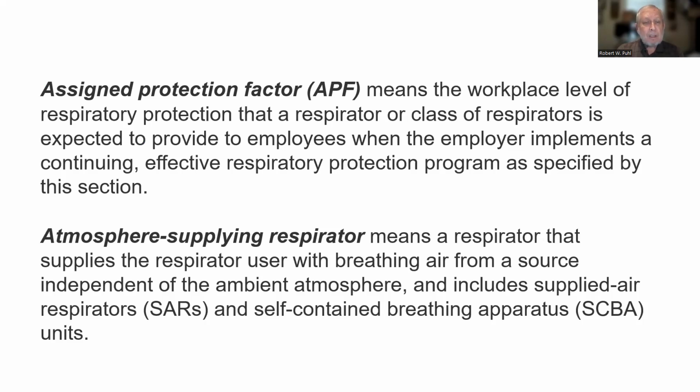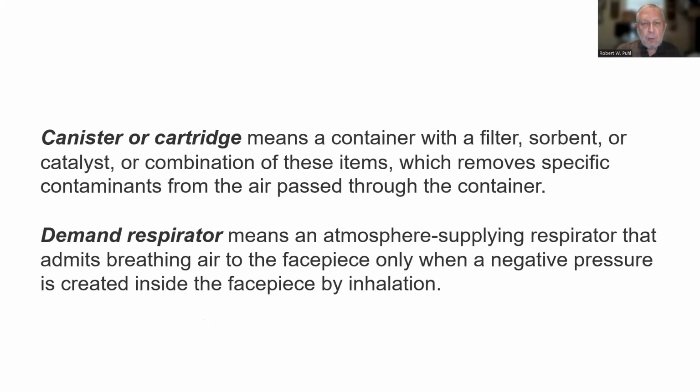Atmosphere-supplying respirator means a respirator that supplies the respirator user with breathing air from a source independent of the ambient atmosphere, and includes supplied air respirators, SARs, and self-contained breathing apparatus, SCBA. Canister or cartridge means a container with a filter, sorbent, or catalyst, or combination of these items, which removes specific contaminants from the air passed through the container. Demand respirator means an atmosphere-supplying respirator that admits breathing air to the facepiece only when a negative pressure is created inside the facepiece by inhalation. So basically you're inhaling it. So it's a demand because you demand more.